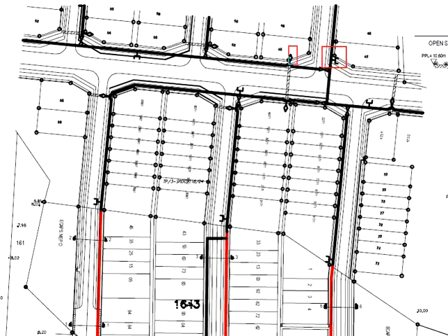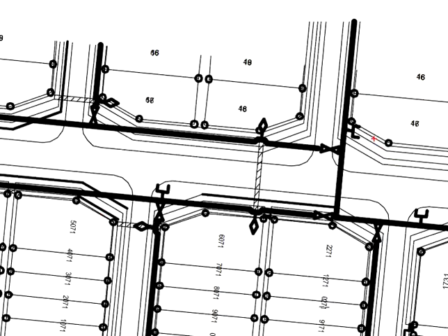As indicated by the symbols, we have fire hydrant, sluice valve. There is a culvert here. That means the water mains passing through the culvert will have to go over the culvert. Now there will be a change of elevations as the pipe crosses the culvert.